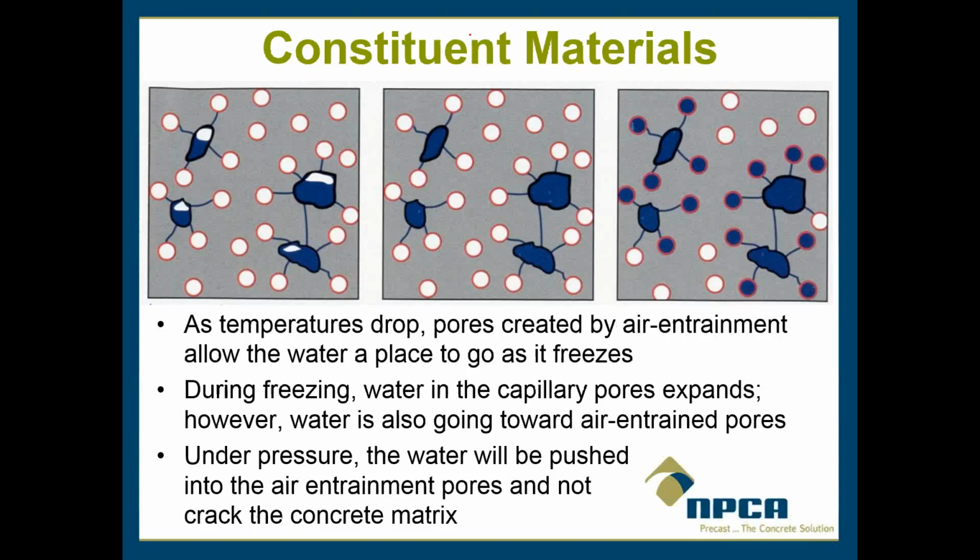So as the temperatures drop, as water freezes, it expands. That extra space needs to come from somewhere. So as it expands, it takes these little air-entrained bubbles, these void spaces, and it can fill up those spaces instead of trying to make room in the concrete.